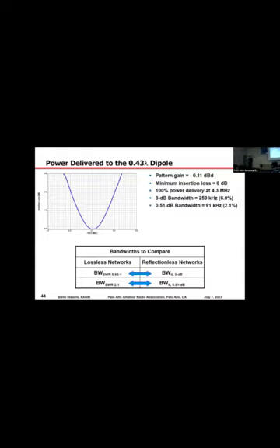Power delivered. This gets to your question you asked about power. The antenna is still narrow band. So now what do I do? If I was to compute the SWR bandwidth, that looks wonderful. But if I compute the radiation bandwidth, it looks terrible. I mean, it's no worse or better. It hasn't changed. So when you do these kinds of comparisons, if you normally are thinking in terms of a 2-to-1 SWR bandwidth, then when you're looking at insertion loss, you have to go with a 0.5 dB insertion loss bandwidth, because those are comparable.